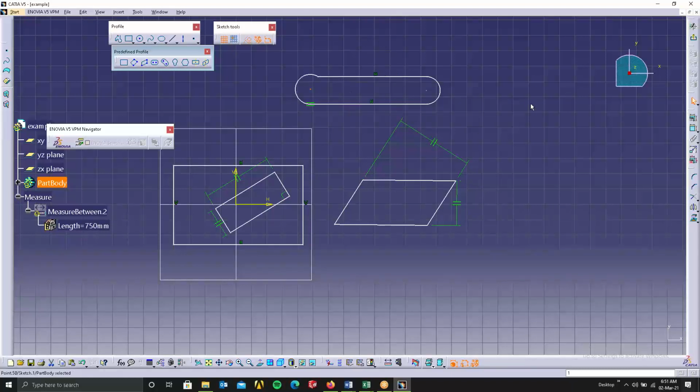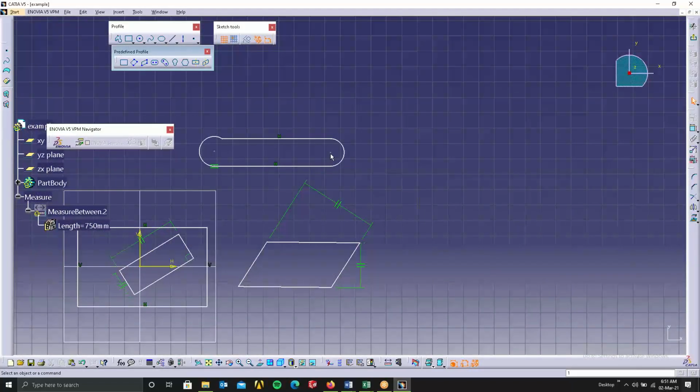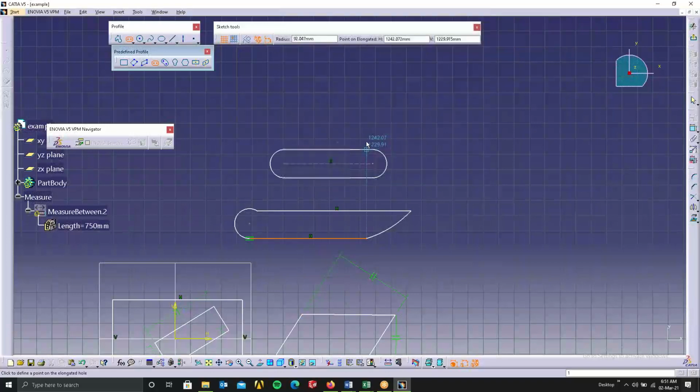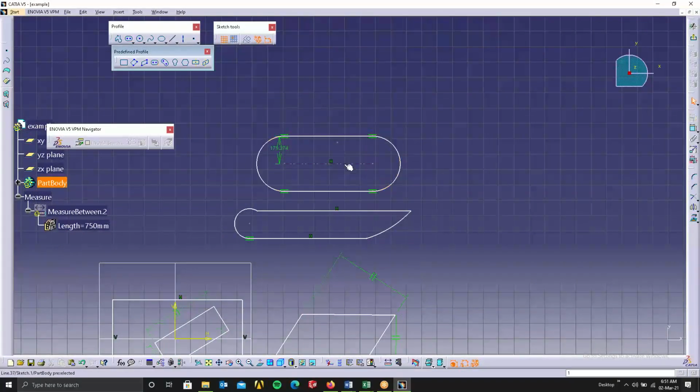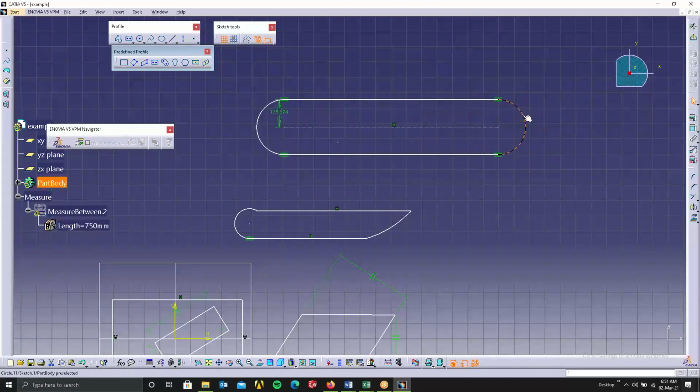So many errors you are getting like this. Instead of this unnecessary thing, I can basically have a tool in place. If I use this elongated holes tool, I basically have the reference line and the inclination angle. Now if I change this, you can see it's properly changing with respect to this. If I want to constrain this also, I can directly constrain this with respect to this.